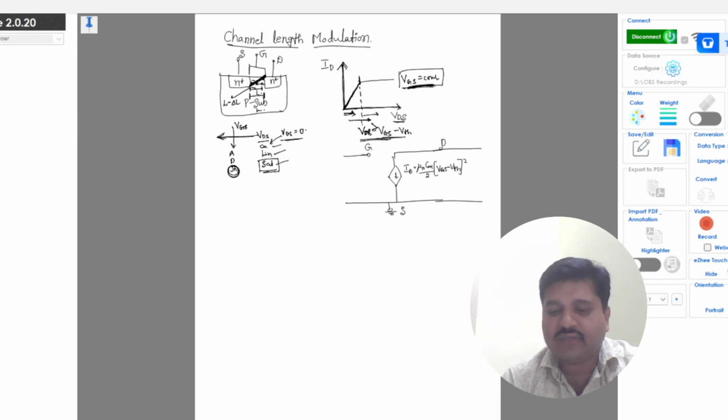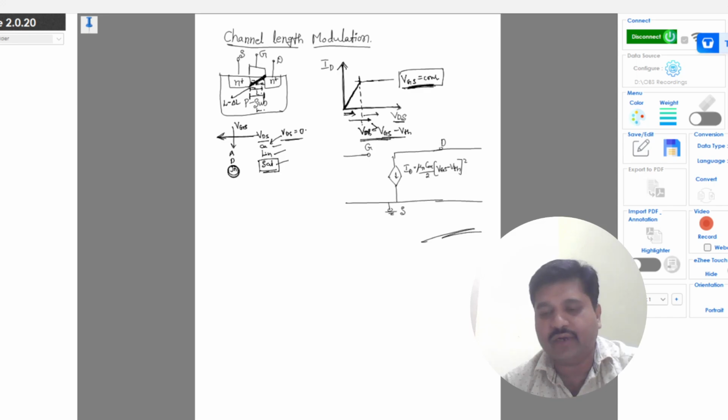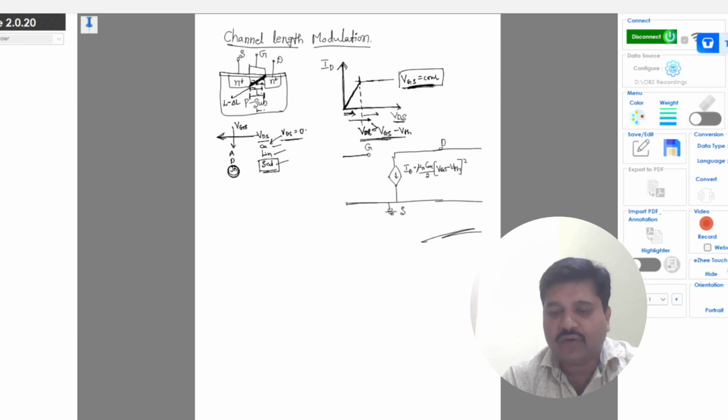Okay, and if we represent the same output characteristics corresponding to this saturation region, this is the small signal model we draw for the MOSFET, an equivalent small signal model representing the MOSFET as a two-port network. The gate to source is open because the oxide layer, this COX, which means SiO2, has a very large resistance, so the impedance is very high. The Zin of the MOSFET will be infinite, which is represented by the open circuit, and hence the input current Ig will be 0.